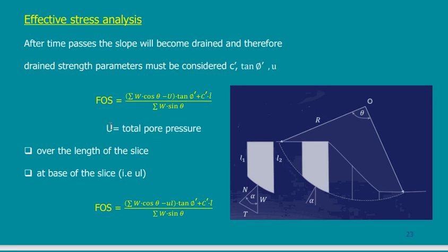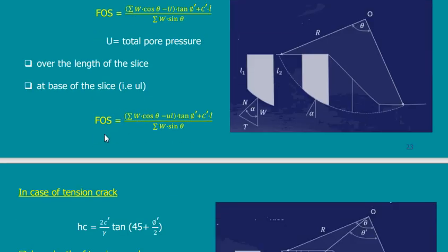I may add the effect of the pore water pressure if I have it, because you know that we need to work on the effective values. You remember from previous studies of total and effective stress, we said that when we study forces in the soil, we study the effective force, not the total, because I don't want the portion of the force that is carried by the water. So in this case, this will be my factor of safety.